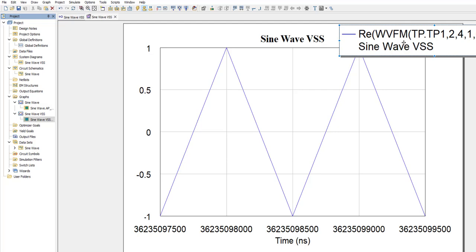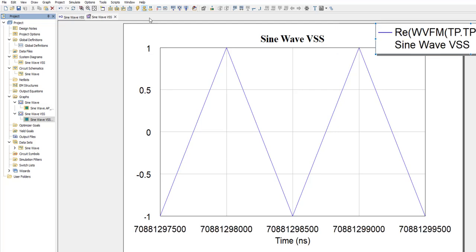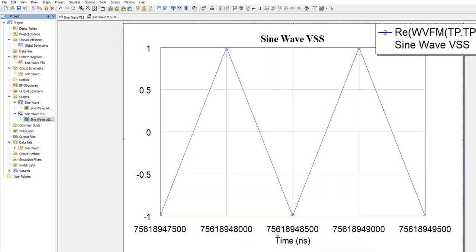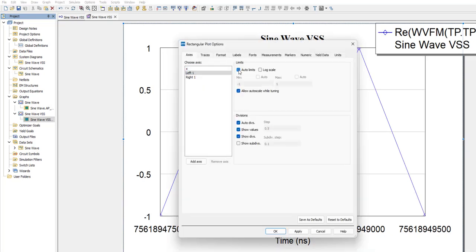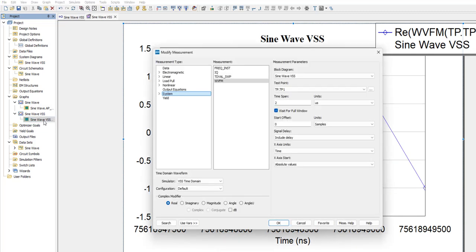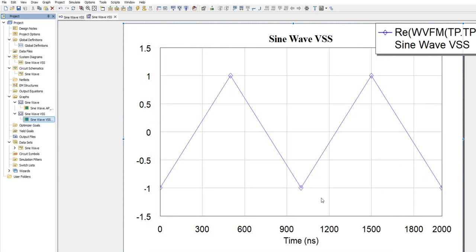As we could anticipate, we get 2 samples per period. And we can see their exact location by adding markers to the trace from the plot settings. Let's also change the y-axis range to make these points more visible. Lastly, let's change the x-axis start to be relative to the left edge, which will make it easier to read the time step between sampling points.